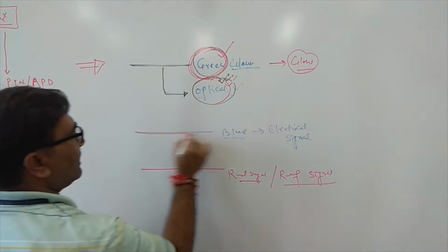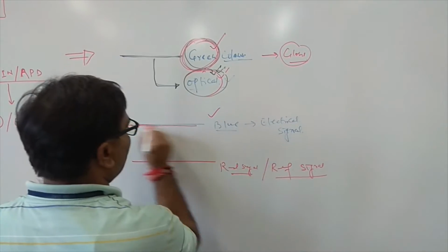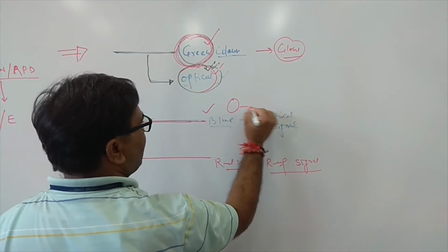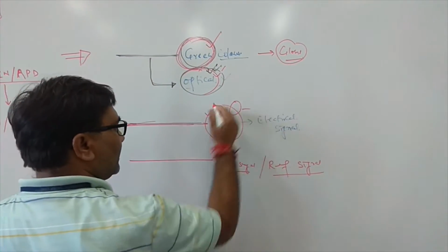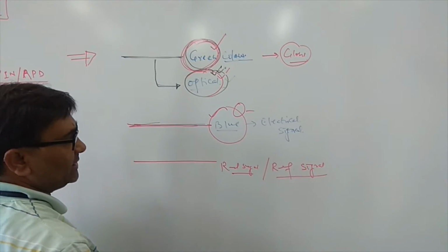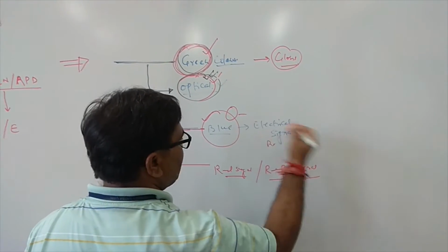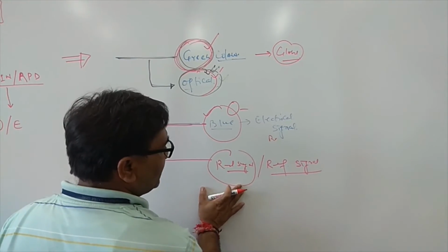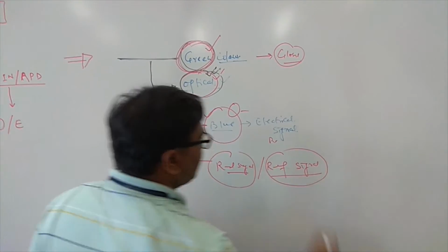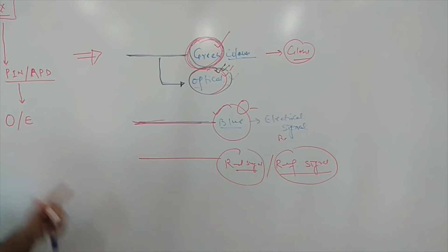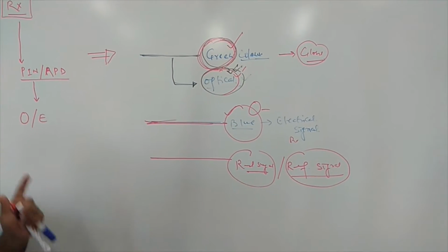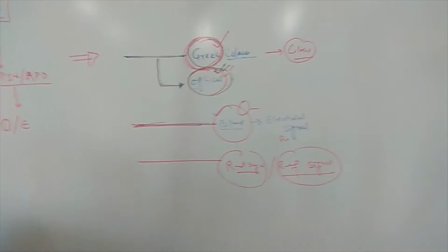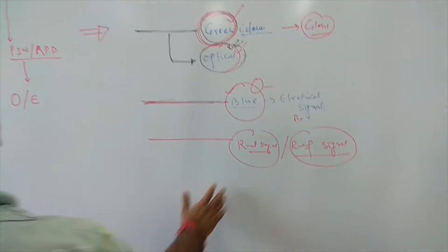If the LED in the blue sections is not glowing, then the problem is in the transmitter part, or the receiver part. If the red is there, it is some default signal or reference. This is the practical scenario. Always remember it throughout your life. This is the basics of your optical communication system.